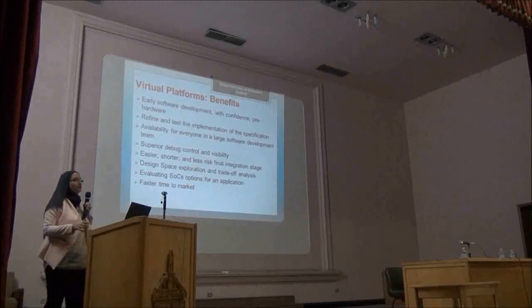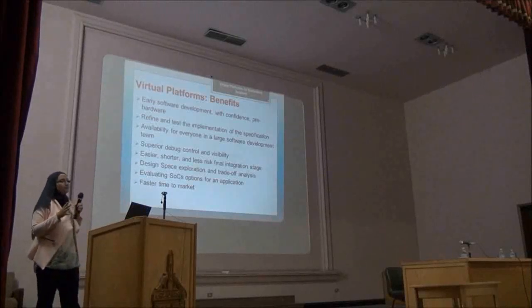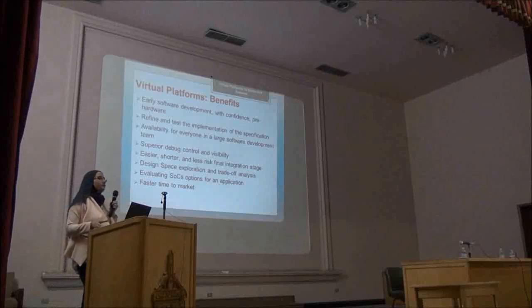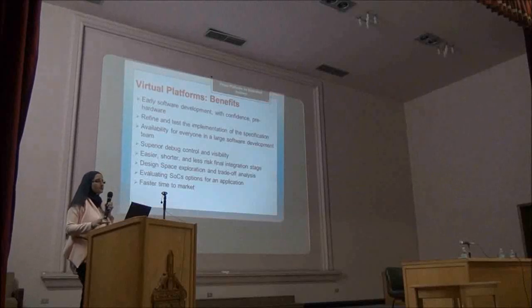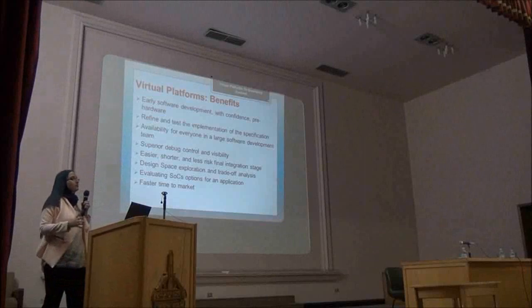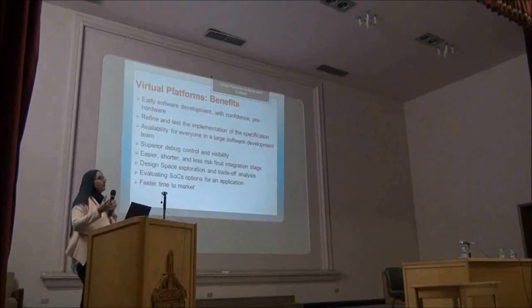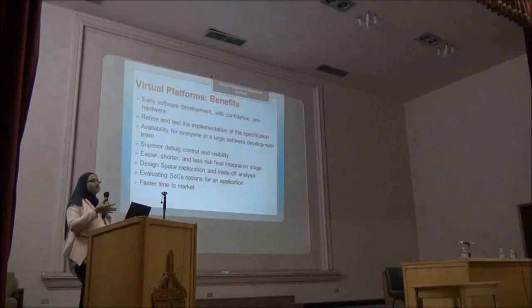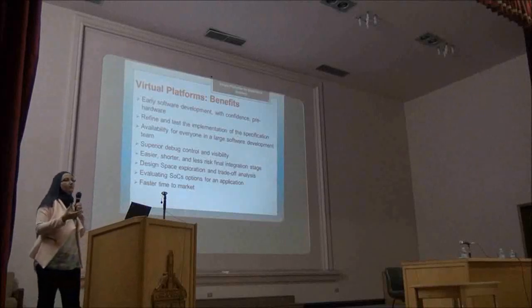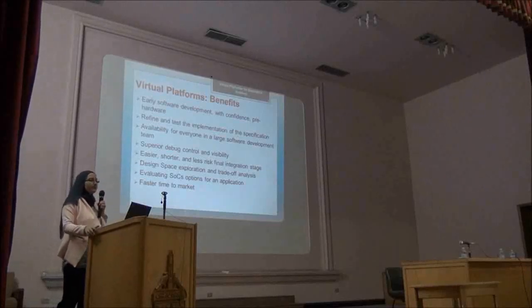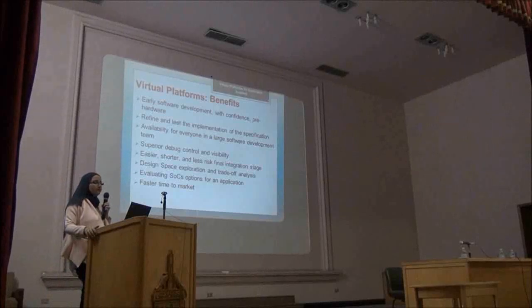It's available for everyone in a large software development team. Everyone only will need his PC or laptop and the virtual platform on it, and he can run the target software. It gives you superior debug control and flexibility. You can insert breakpoints not only in the software, but in the virtual platform, in the software components for the hardware devices at the same time, so you can be debugging both the software and hardware in parallel, so it gives you a greater visibility for the overall embedded system.